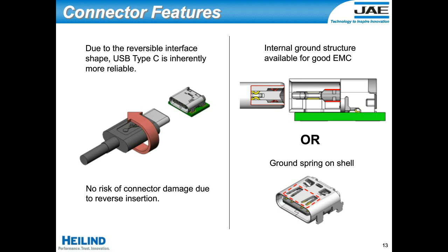Another thing to note that's fairly consistent inside of new I/O connectors is the fact that all the spring contacts are located inside the plug connector instead of the receptacle connector. Basically, the main reason for that is that the spring contacts are the side that moves and the side that's more likely to fail. The plug side is typically the cheaper device, so it'll be an accessory cable, whereas the actual host device is probably going to be the more expensive side, so you don't want that side to have any failures.